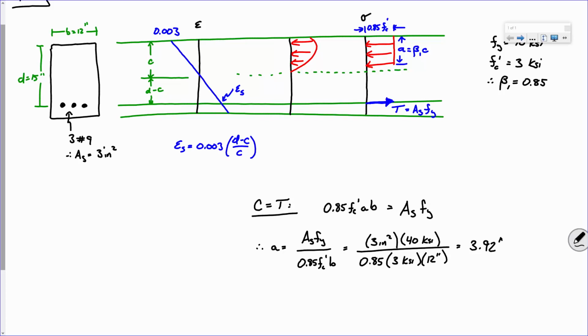Now my moment arm. Well, my moment arm is going to be the distance between these 2 forces. So this compressive force is really going to be collapsed, centralized right there. Make sense? If you have a uniformly distributed load, you can collapse that into a single point load in the middle, right? So my question to you is, how far is it from here to here?